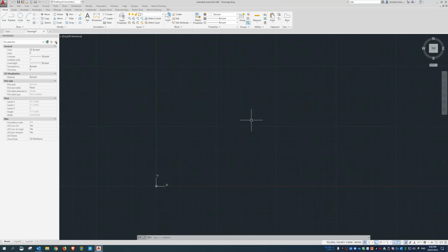Okay, and while I remember it, when you pick something, there's an element called a pick box. So if I erase something, that's this white box you see in the middle of the screen. So if you type in the command pickbox and I give it a value of 8, then you can see the box gets a bit bigger. Just to show you an extreme value there, if I go 20, you can see how big that pick box is. I'm running a 1440p resolution, so I'm going to go back down to 8 because that's a nice sort of size for this as well.